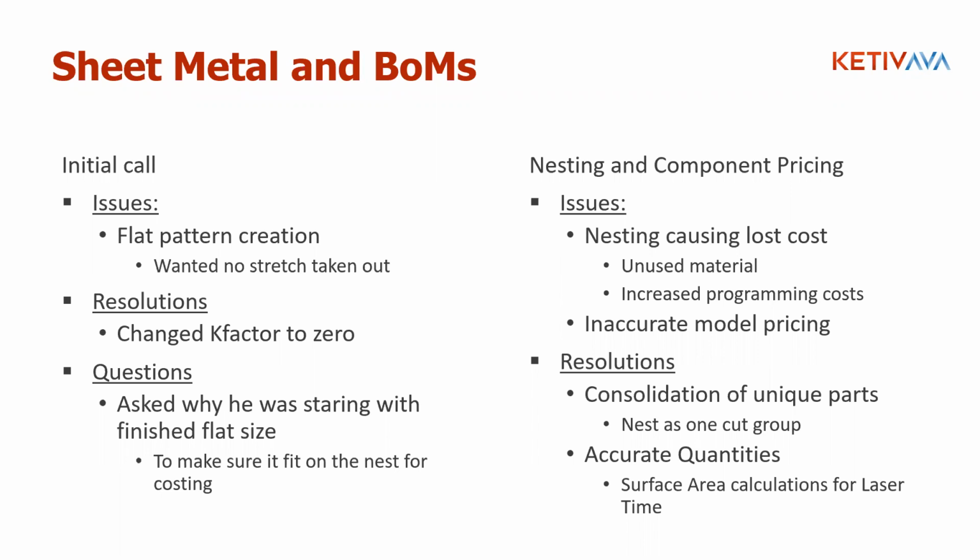Yeah, I've done a couple of AVAs on that specifically. It's really cool when you can take a full-blown assembly with like 10 sheet metal parts and hit the nesting button, and it'll make the nest for all of the parts. It'll group all of the like thicknesses together, and then it'll give you all of your various sheets. So just something to keep in mind, as the products evolve, it might be worth it to explore what you currently have and how maybe you could use it in your workflows.